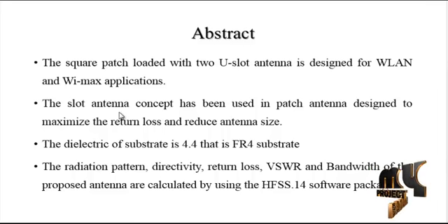In this proposed work, a square patch loaded with two U-slot antennas is designed for WLAN and WiMAX applications. The slot antenna concept has been used in patch antenna design to maximize the return loss and reduce the antenna size. Here we are using FR4 as the substrate, whose dielectric constant is 4.4.